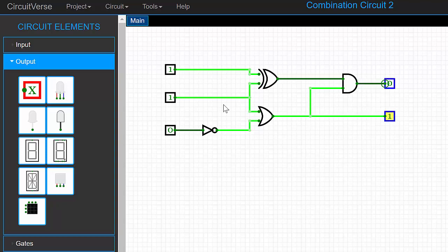Now, as I said before, there's probably no clear purpose for this circuit, but it is useful to see. As we start to trace it, you can see the sections which have got electricity going through them, which is true, go light green. And so you can already see that in the state of 0, 0, 0, we've got a particular result here. And then I want you to get into the habit of being able to record the truth table accurately. So put the one here that changes the power to a NOT, and there's basically no power coming through when we get the zeros there.